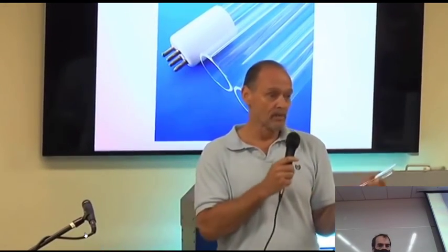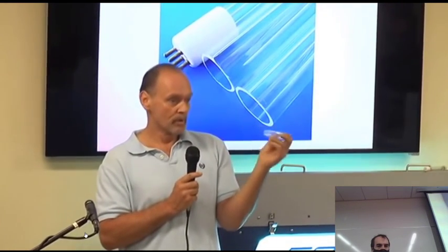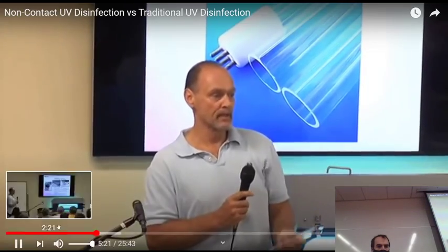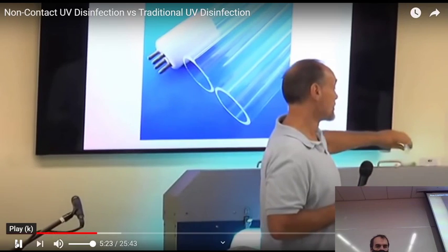And over a period of time, you have maintenance issues to keep this clean. So the squeegee fails, or you can't get the boundary layer off. Now you have to lift that lamp rack out, acid wash it, take the unit offline, then put it back in. That doesn't sound like fun.